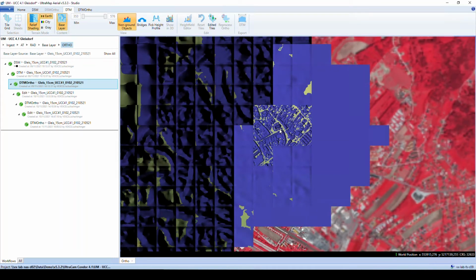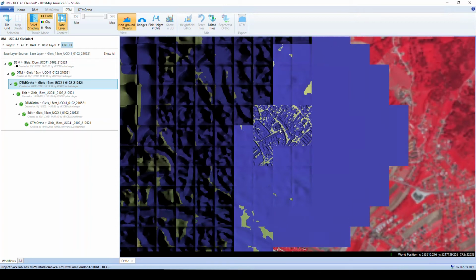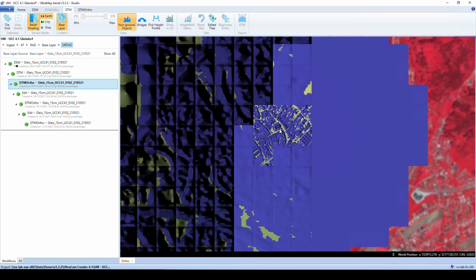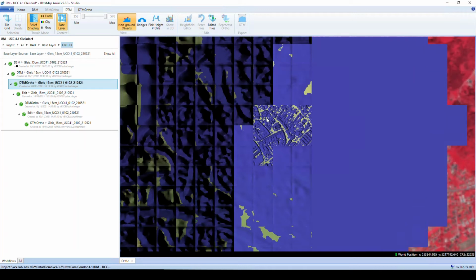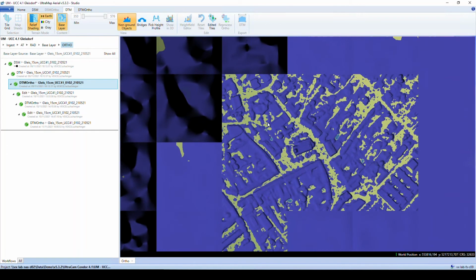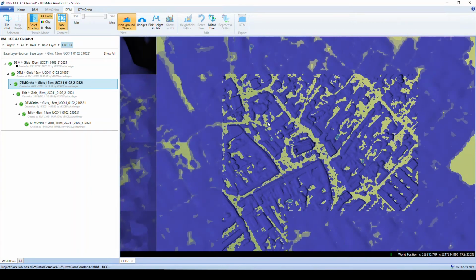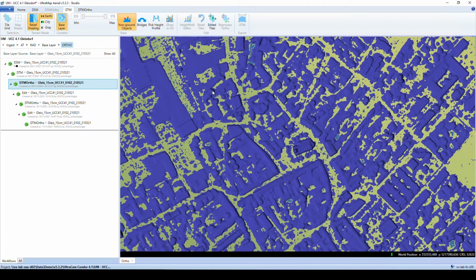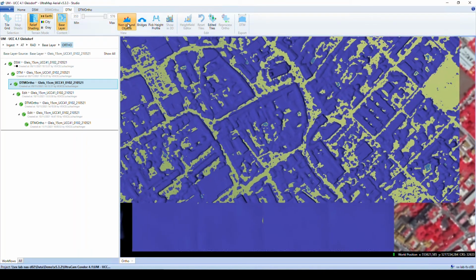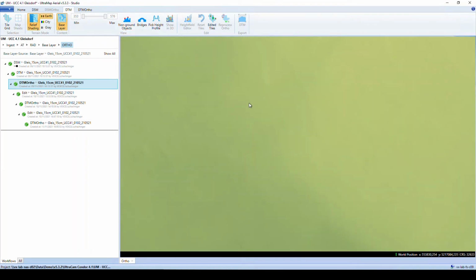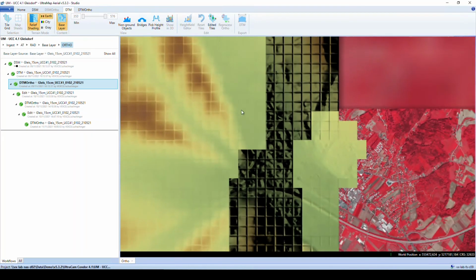Using RGB and near infrared, the software tries to identify buildings, vegetation, bridges, and so on, and then eliminates all these elevated objects from the DSM. In that way, the software is able to clean the DSM so that there are just pixels of bare earth remaining, and then fill these holes to make a flat terrain possible.